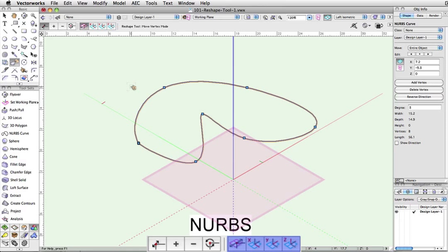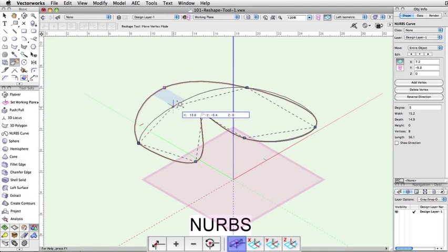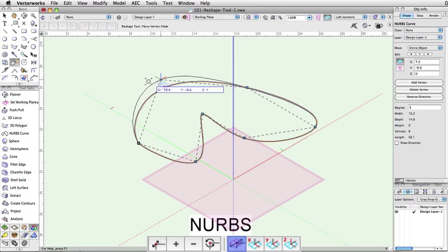These allow you to constrain your movement to a particular axis, effectively making it impossible for you to accidentally align a vertex to a snapping point inadvertently. Working plane will force the vertex to remain in the same orientation to its current working plane, or the ground plane, if a working plane was not assigned. It's the default mode of the Reshape tool for these objects.